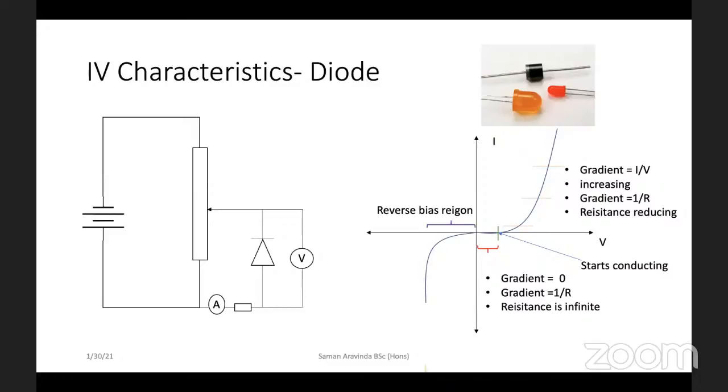But after a certain while, the junction breaks. Now, this diode is made using P type and N type semiconductors, so you don't need to know about this breaking of the junction. So the junction breaks and the minority carriers start to move, maybe either holes or electrons. When the minority carriers flow through, there will be a very high current. So we say the diode is broken. That particular voltage where the diode breaks, we call the breakdown voltage.